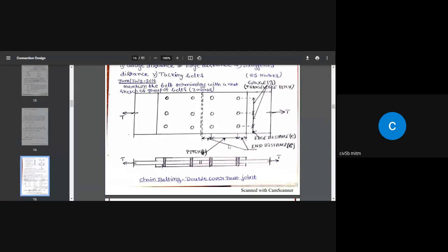So what is P max? What is the maximum distance you can cover? Again, if you go to the next page, page 74, it deals with maximum spacing. One is maximum spacing for pitch and the other is maximum spacing for gauge. So remember, I'm going to apply the maximum spacing for the pitch part, and that is safely and adequately going to apply for the gauge as well.